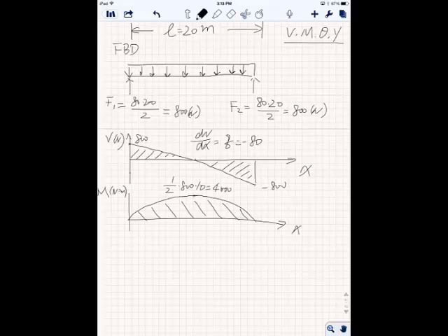Okay, so the next thing is theta, which is slope. Now slope, like we mentioned, is also related to bending moment, which is one integration, right? So over here, we have shear force V. If you do integration, I just use INT, all right?